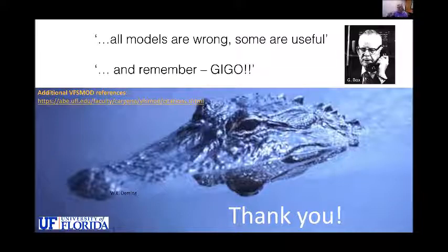So daily we can adjust the water level, the distance from the surface, to be able to calculate the impact. For days where the water table is deep enough, there is no effect. For days where the water table starts coming into that critical, sensitive region, then it is incorporated. And what we are proposing, the way it's going to be automated on SWAN, is it will run all in parallel, so buffer with and buffer without, when the user requires water table. So we can do a comparative analysis between the effects of that potential factor.